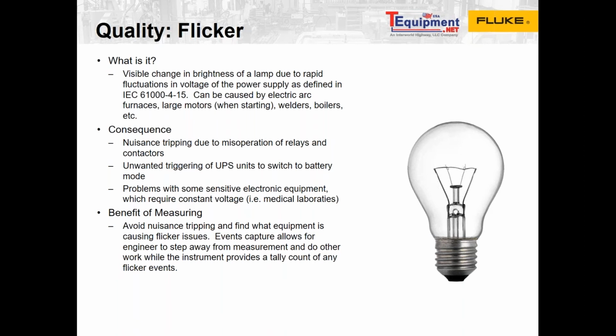And we covered health issues on that end. That's why we look at it. And honestly, I think in the US, we don't tend to pay attention to our health too much, so it's not a huge concern, flicker. But flicker can also cause not just health issues, it can cause nuisance tripping. It can also cause unwanted triggering of your backup power supplies, and may cause you to drain your batteries on your backup power supplies, because the UPS will be switching on and off. And then some electronic equipment is sensitive, such as the electronic equipment in hospitals or medical laboratories. So the benefit of measuring flicker is avoiding those situations, and also pinpointing what equipment is causing the flicker issues.